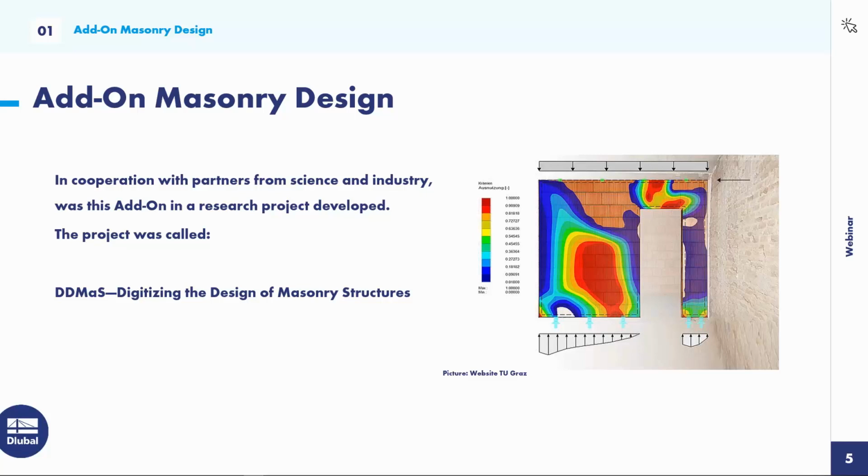Topics like BIM, building information modeling, and the exchange of models or systems between an architect and special planners, or the creation of capacity curves for the whole building to estimate earthquake resistance played an important role there. Now it is also possible to compute, I will call it mixed structures, for example, for concrete and masonry in one 3D model.